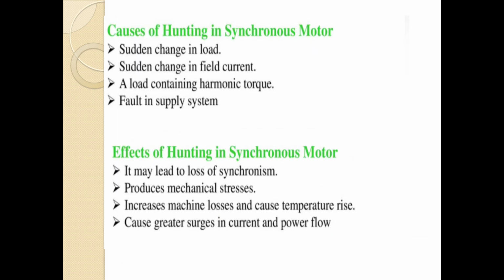Causes of hunting: sudden change in load, sudden change in field current, harmonic torque, and faults in the system.